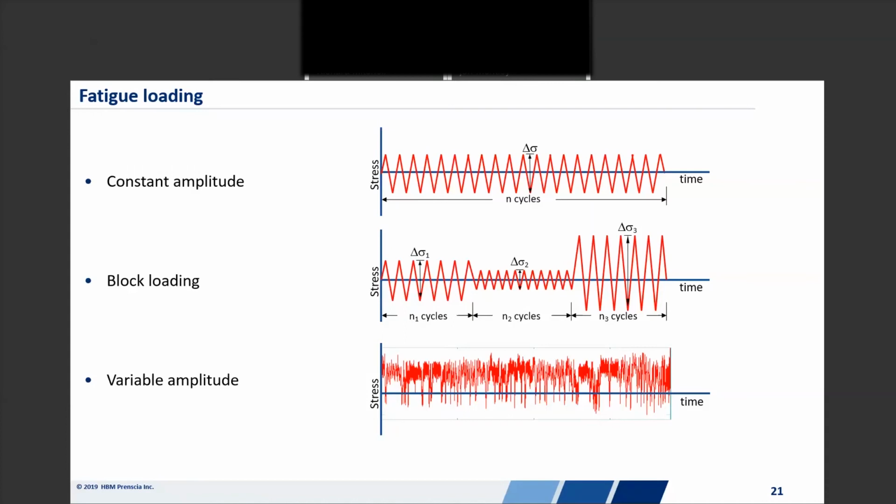In the real life scenario where I have variable amplitude loading, with loads changing over time, it's computationally too difficult to do by hand. This forces us to use the procedures that were developed over the last 100-some years: characterizing cycles with rainflow counting, coming up with ways to accumulate damage cycle by cycle, and looking at the arena of plasticity in the overall fatigue calculation.